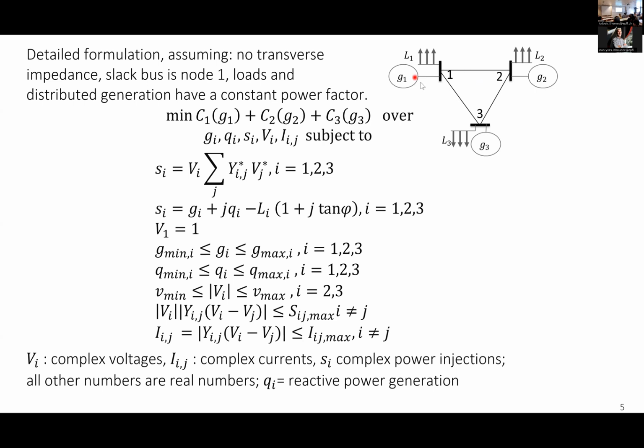So if I do this in this grid, I will set up G2, G3, and L1, L2, L3 will also do what they think they do, but in reality, there will be small differences between the values that I'm using in the planning and the instantaneous value that changes all the time at high frequency. So for example, if I turn on the boiler in my lab here, I increase the power consumed by the grid of EPFL by a minuscule amount. Of course, nobody knows exactly when I will turn on the boiler. So there are fluctuations due to randomness that, of course, we don't want to forecast exactly. Those microscopic fluctuations are balanced by a number of things, but in particular by the slack bus. It's the job of the slack bus to inject more or less than planned in real time. So that is what this thing will do here.